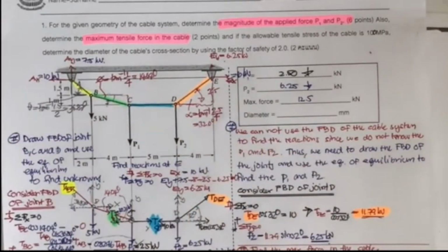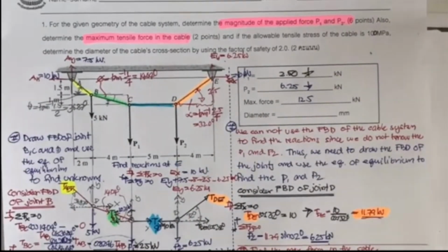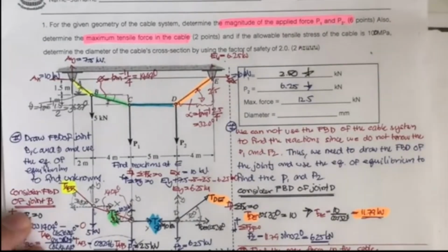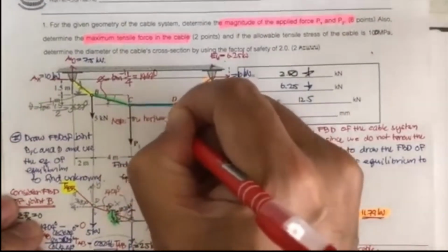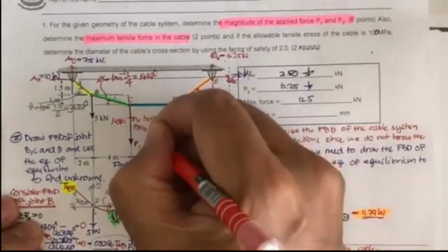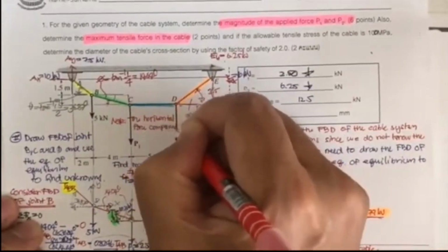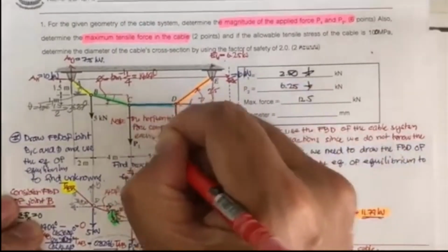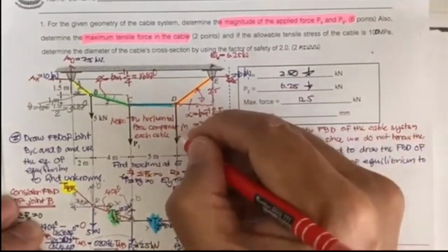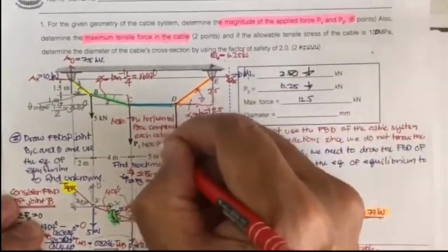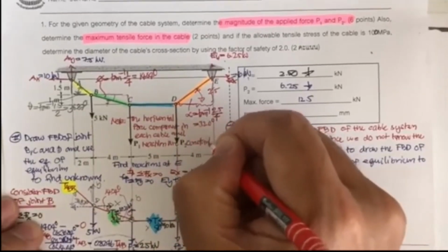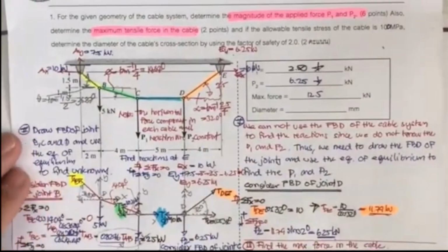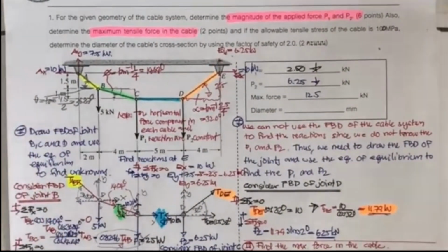If you project all the horizontal forces, you may see that the horizontal force component in each cable and reaction are constant. They are all constant, and this is important. It helps us to check whether our calculation is correct or not.